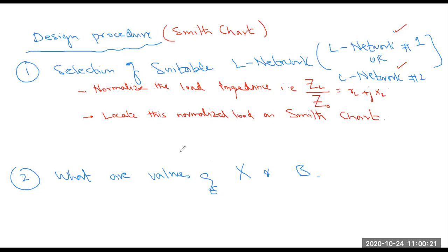Once I mention all of the steps, then we will solve one problem, and then you will see the application of all of these steps. Okay. So once you have the normalized load, you will find the location of this load on Smith chart, and this is something which we have already covered before midterm.